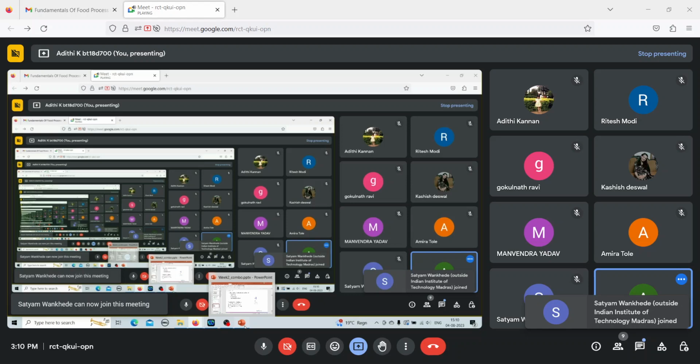First, because you can control the amount of strain that you give on these. You can control the amount of shear stress that you give on these fluids based on the angular velocity of this rotation. So if you rotate very fast, you can give more stress. If you rotate very slow, you can give less stress. So the amount of stress that you give on the fluid can be controlled by the rotation speed. The shear rate is directly proportional to the rotational speed of the system, so the shear rate can be controlled.